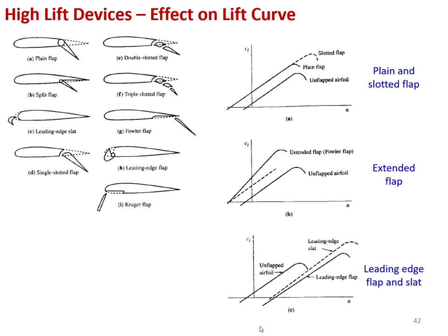Depending on the type of mechanism, you can increase the stall angle of attack, you can increase the lift coefficient, or you can change the zero lift angle of attack and the slope. So the point is to delay the stall, or to have more control over the stall. It's a better word to use.